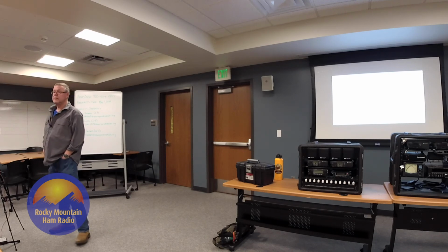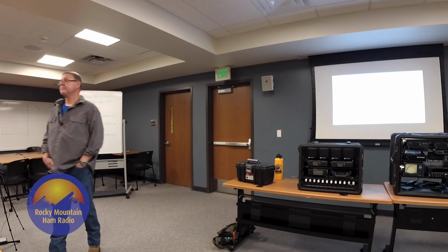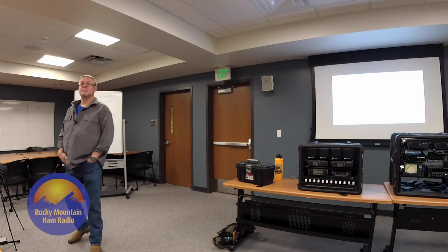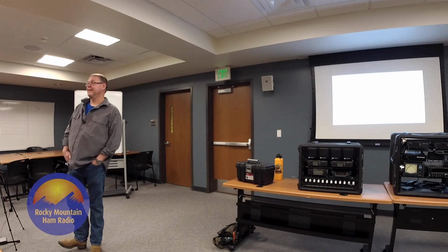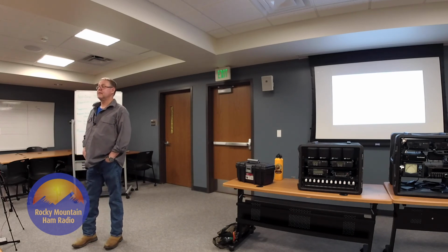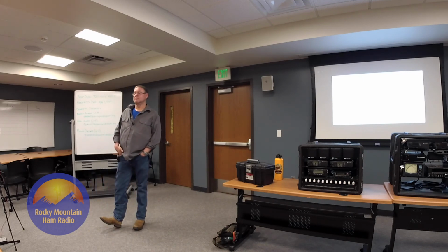It's a copy of the dipole. It's basically a dipole with a 12-to-1 balun in the middle and some 500 ohm resistors at the end of it with down leads that go to ground rods. And it's 180 feet long. I think it's 90 each side, so it takes a lot of room, but you'll talk on any band, 1.8 to 30. Chameleon's version has all the different terminating resistors at the end of each dipole leg. It's 60-foot legs on each side of the dipole, so it's a little bit more compact. But I think they must use some gold plating because it's about $400. You can find the Harris's on eBay for $300, and they're phenomenal.